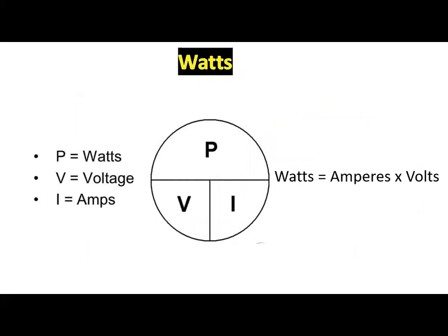What is an electrical measurement that is calculated by multiplying the amperes by the volts? Although watts are not measured when servicing vehicles, it plays an important role in electrical system design. For example, if the total amperage load of all the electrical accessories on a vehicle is 250 amperes in a 12-volt electrical system, the total watts of energy required are 12 volts multiplied by 250 amperes equals 3,000 watts. Therefore, the charging circuit on the vehicle must be capable of supplying over 3,000 watts.